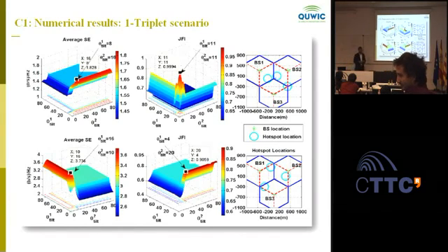How does this solution relate to beamforming schemes in which you have maybe 2 antennas and you can digitally shift the beam? That's a good question actually. To give you a straightforward answer, it has nothing to do with beamforming. Beamforming is something separate. Beamforming assumes that you are able to shape the pattern of your antenna and have multiple lobes. This solution assumes that you have only one lobe.